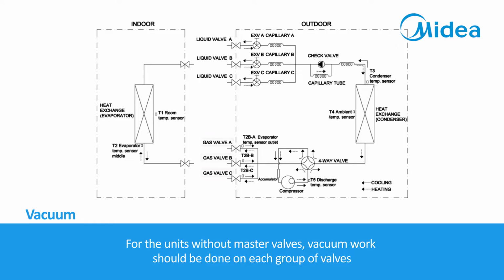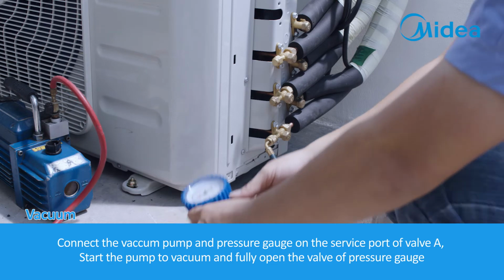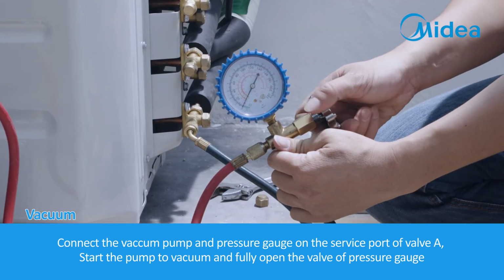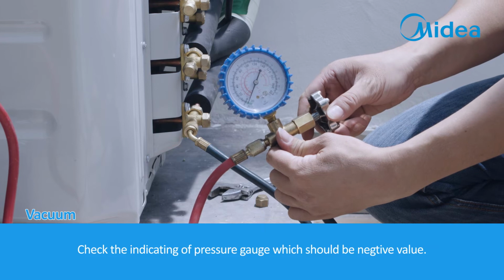Vacuum. For the units without master valves, vacuum work should be done on each group of valves. Connect the vacuum pump and pressure gauge on the service port valve A. Start the pump to vacuum and fully open the valve of pressure gauge. Check the indicating of pressure gauge, which should be negative value.